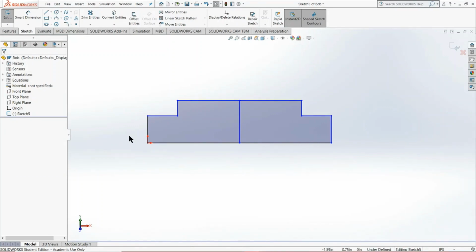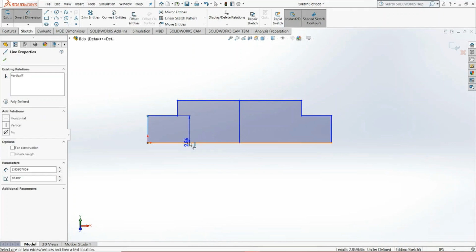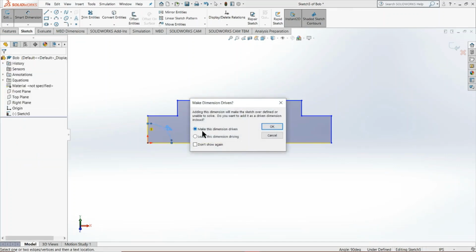Now, finally, I want to touch on a previous point I made, particularly when it comes to rebuilding your sketch and over-defining your sketch. So what I'm going to apply is a dimension here, and we'll put it as an angle dimension, an angular dimension. And you may be asking me, you're saying, Nima, that angle's already at 90 degrees. Why would we want to put another dimension in there? Sometimes we aren't thinking and we do so.